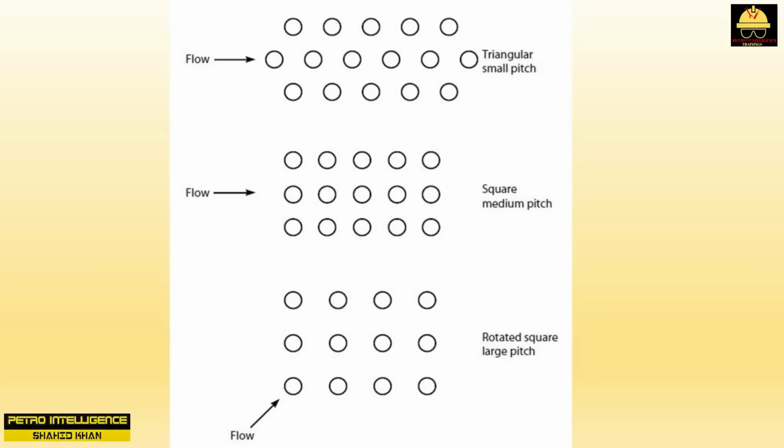Selecting proper tube pitch. From a theoretical heat exchanger perspective, the triangular tube pitch shown in the picture is best. The term pitch refers to the geometry and distance between the holes drilled into the tube support baffles. A triangular pitch means the holes are drilled in the pattern of a 60 degree equilateral triangle. For example, we might have a 0.75-inch tube OD on a 1-inch triangular pattern.